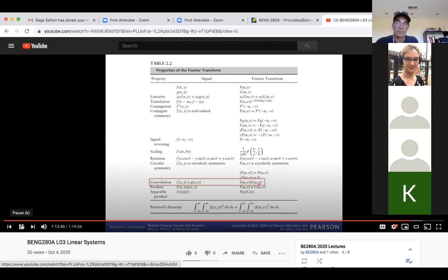So in audio, say we have frequencies from 1 hertz up to 20 kilohertz. And I look at my signal and I say, you know what, I got too much noise up top here. I'm getting this really high frequency noise. I'll smooth this signal. In the time domain, you would convolve that time domain signal with, say, a Gaussian, and it would just smooth that signal in time. In the Fourier domain, it's equivalent to taking the Fourier coefficients of your signal and depressing the high frequencies. So it's a low pass filter. A low pass filter is just a smoothing function in the spatial domain.